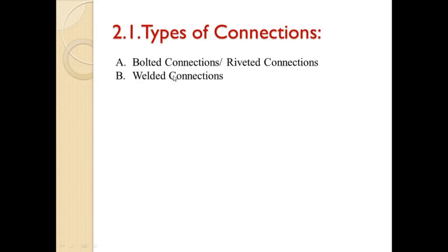First is bolted and second one is welded connection. One more is there, that is riveted connection, but riveted connection is obsolete nowadays because it requires preheating and more labor for supervision and is noise polluting. Hence, bolted connections are preferred over the riveted connection. So let us see the first part, that is bolted connection.